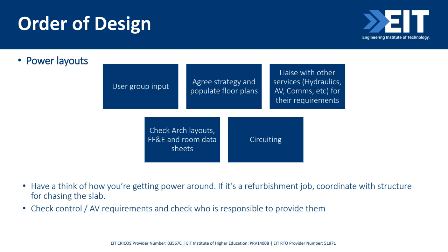So power layouts, what goes on them? First of all, we need to ask the client what they want. Maybe they really want X number of power outlets, or maybe they have specific equipment that they're going to be installing. Then we want to know how we're populating those floor plans from a drawing perspective. And are we providing power for other services, or is it just general power? Maybe there's lifts or hydraulic pumps, hot water units, communication racks. We need to coordinate with them and provide power where they need it.